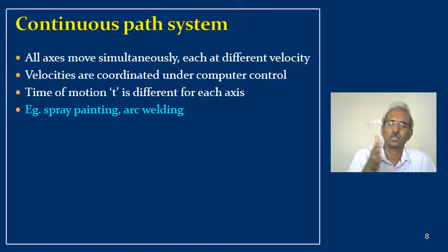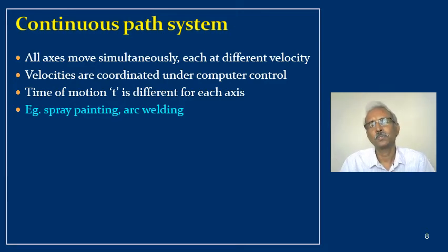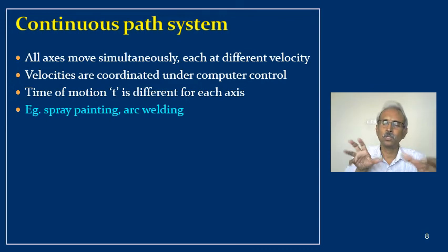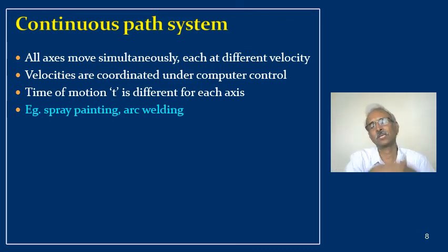So turning, only one axis; facing, only one axis. Now if you want to do a taper turning operation, you have to control both the wheels simultaneously so that it takes an inclined path. That needs a high level of eye and hand coordination. Because it's a little difficult, that's the reason you add a taper turning attachment.